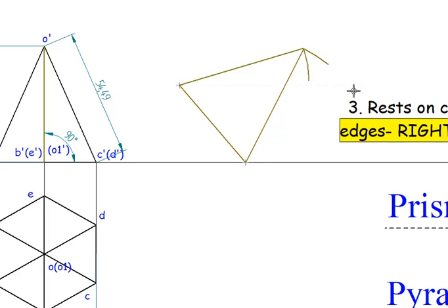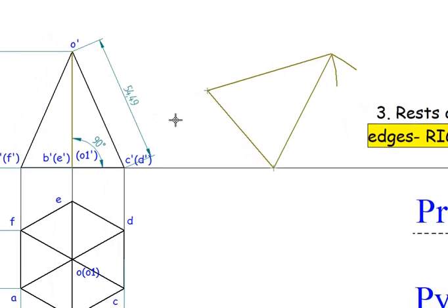So now I've just drawn a line. Now this is exactly the midpoint. So you can just take this measurement and cut an arc and draw this line. So from here I'm going to draw this line. So now I said that the angle between this and the base should be 90 degrees.